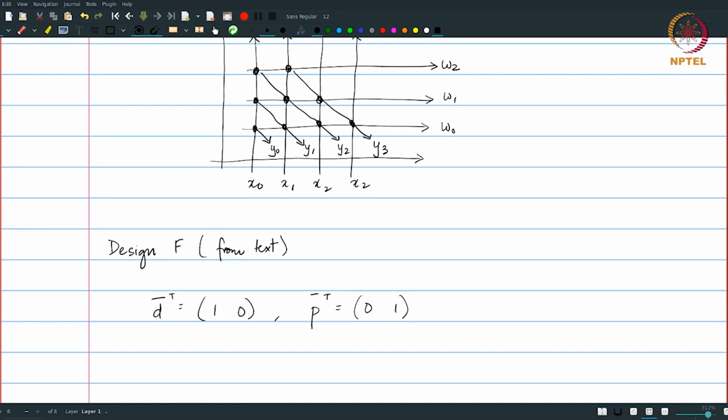Not all of them have physical meaning, and what we'll find is that in a lot of cases we might also have to make certain kinds of adjustments to our dependence graph for the interpretation to be meaningful. But in this case we will just stick with the simplest possible interpretation and see where it takes us. I also need to choose a value of S. The only constraint on S is that S transpose D must not be equal to 0. One example that I can choose is 1, 0. As you can see, 1 minus 1 would also be perfectly valid, 1, 1 would be perfectly valid, etc. All of those would give me S transpose D not equal to 0.